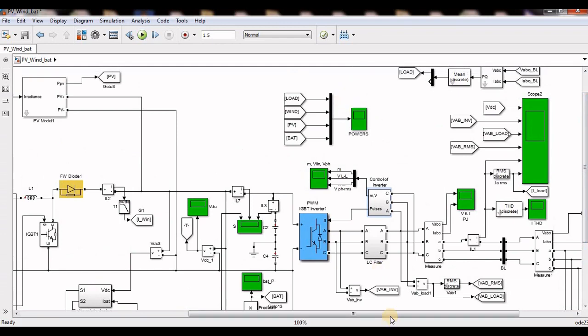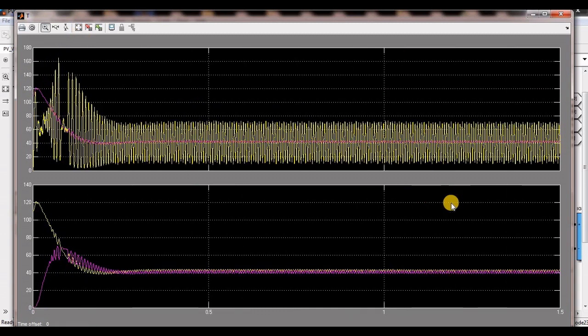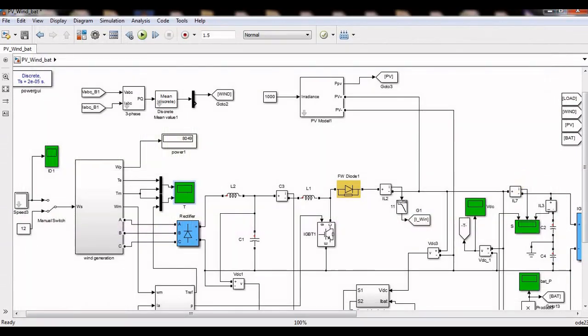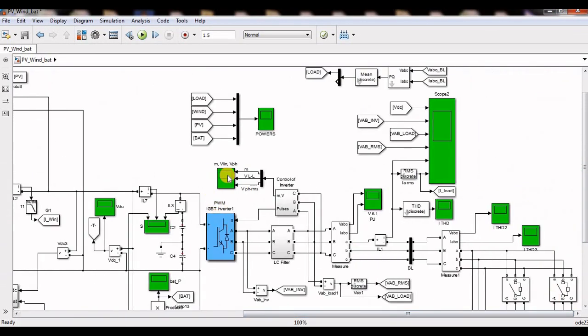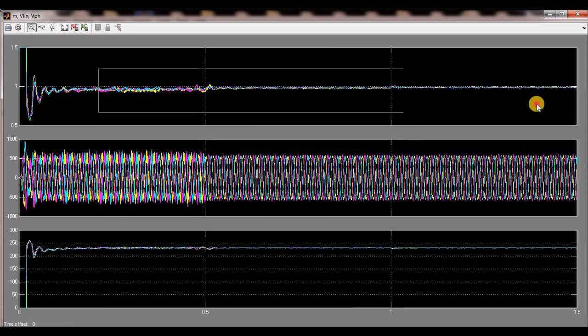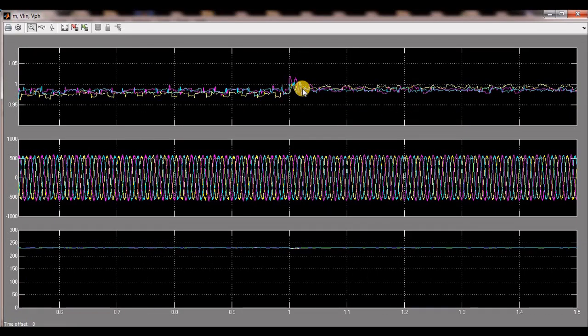So the power I explained, and you can see the MPPT is regulating fine. The MPPT is working very well. The torque and reference torque are both matching, and you can see my RMS voltage and the other results. The first one is the modulation index. I am always maintaining the modulation index based on my load, so it is changing. With more load, more modulation index is required to maintain the AC RMS voltage at the PCC, because more load means more drop, and a higher modulation index can increase your inverter voltages. So after the drop, the PCC gets the regulated RMS voltage.